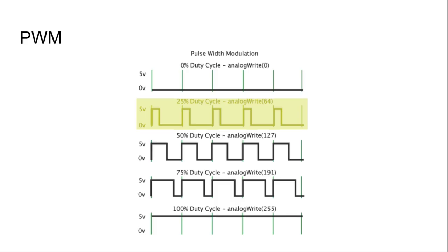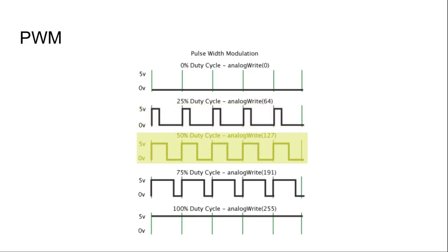Of course, depending on the analog reference set on your Arduino board, you should first know which is the target value for the high signal, because as we have discussed in a previous video lecture, the target signal could be 3.3 volt or 5 volt, and you can also check that using the analog reference pin, or simply read the datasheet.